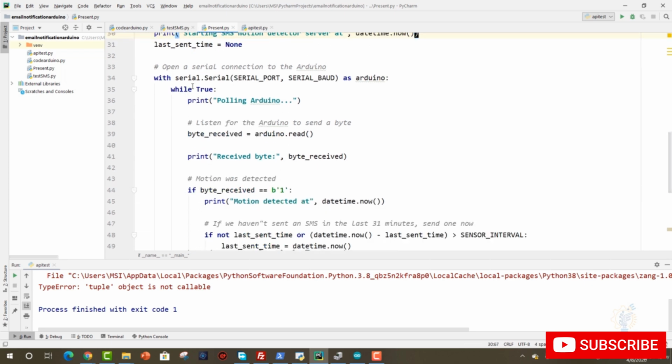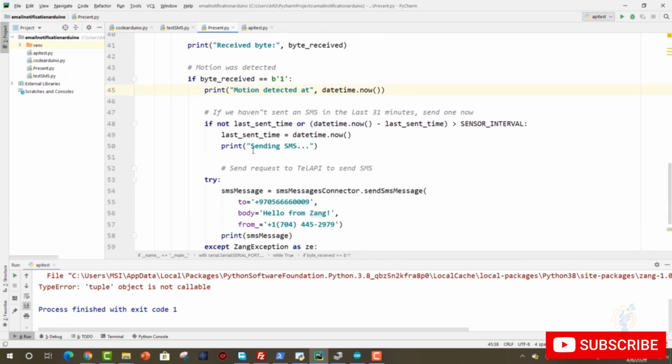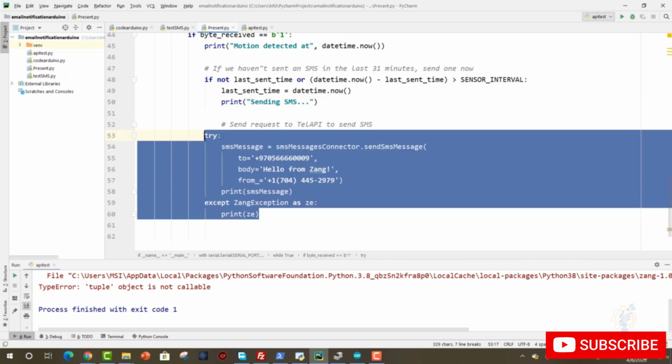After that, we are opening up the serial communication and storing the incoming data from Arduino to this variable, byte received. Then we are comparing. If byte received equal 1, then motion is detected and we need to send the SMS, and we are going to execute these lines to send that SMS.